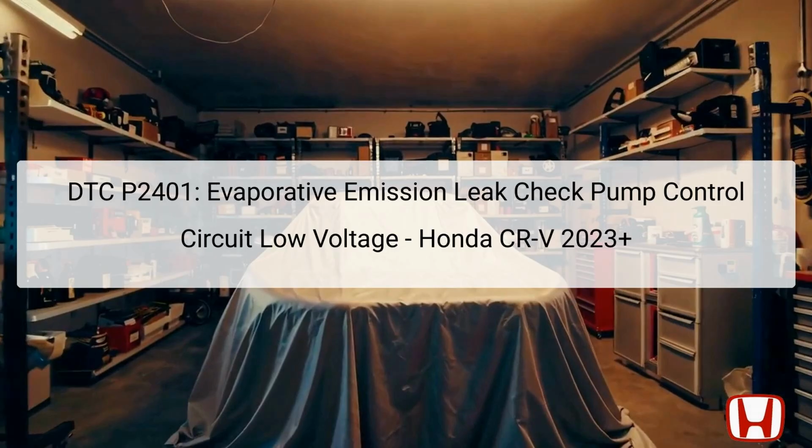The PCM acts as the central computer that monitors and controls various engine and transmission functions. When it detects abnormal readings, such as a low voltage output while the pump is supposed to be off, it triggers this DTC to alert the technician.